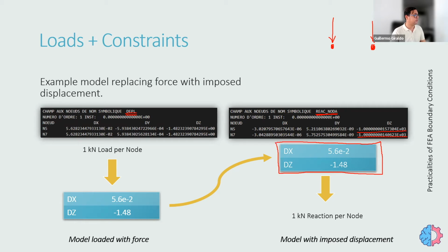That's an option of the FEA solvers. So as inputs, you don't have to only apply forces, but you can also create the deformations by applying what is called imposed displacements. So Jeremy says, having to set forces at this node is an example of the input file depending on the mesh, which was discussed in the very previous talk about things.